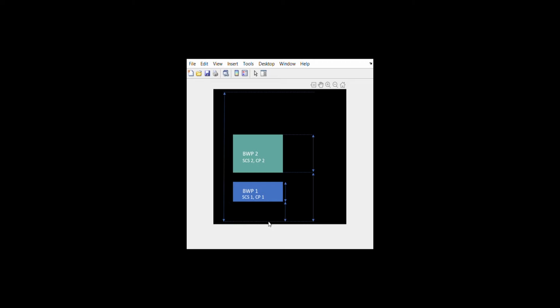Okay, so first you have to define for the first bandwidth part how much is the offset from this dashed line. Okay, this one, and you have to know the y-axis is the number of resource blocks, and this corresponds to the time axis. So in this one we show that the bandwidth part is at an offset of this much. And then this, the total length in resource blocks, corresponds to how many resource blocks are defined for this bandwidth part.